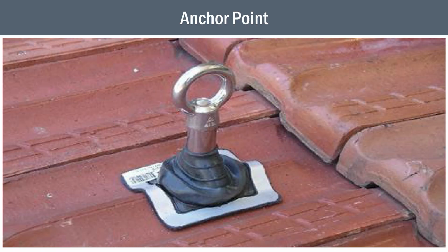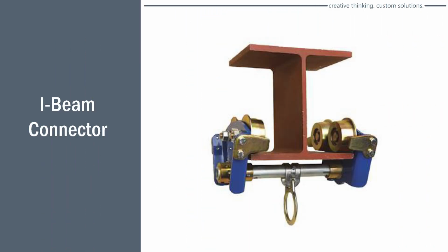There are engineered anchor points and there's non-engineered anchor points. You get into the ANSI standard, I believe it's the Z359, discusses more about that. Here's another picture. Here's an I-beam. I like to show pictures so people can get ideas of what they could use at their facilities.